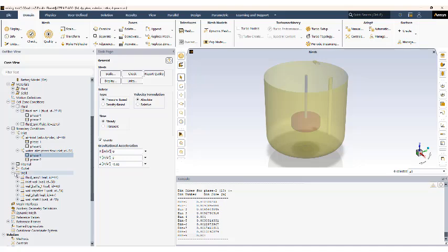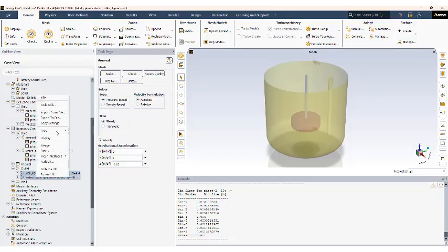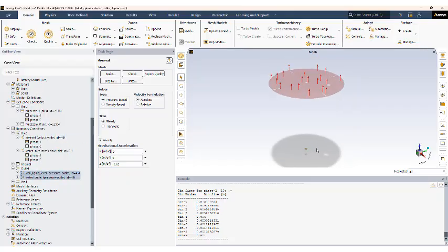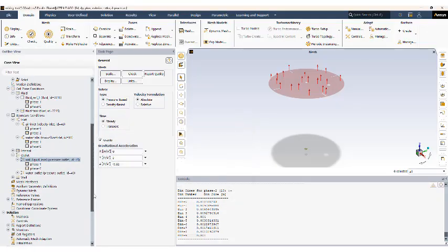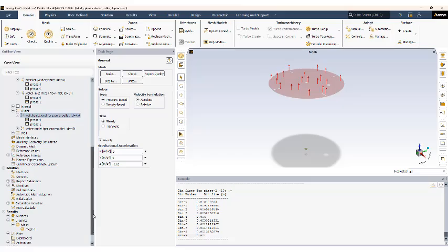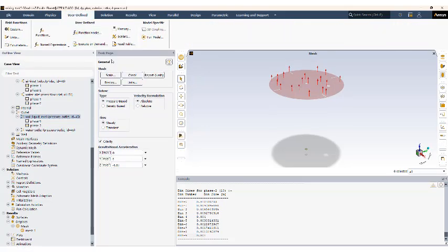So I've defined the wall, MRF conditions, both boundaries, both outlet boundary conditions are also defined as pressure outlet. So not much to it, basically using the defaults. And yeah, so basically what I need to do now is also define some report definitions. So it's good for especially checking convergence, and if you want to make some adjustments to the model